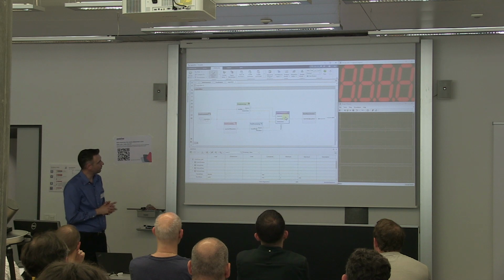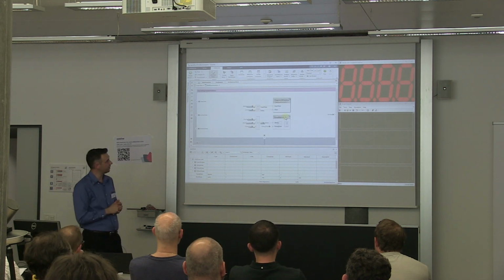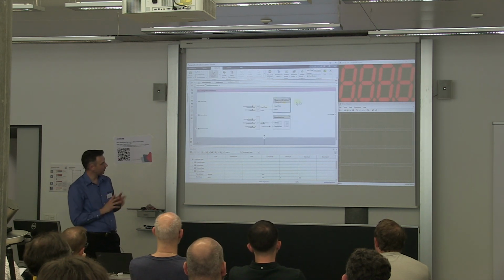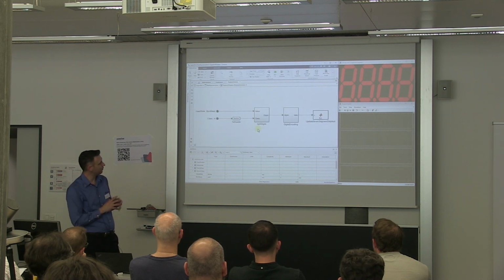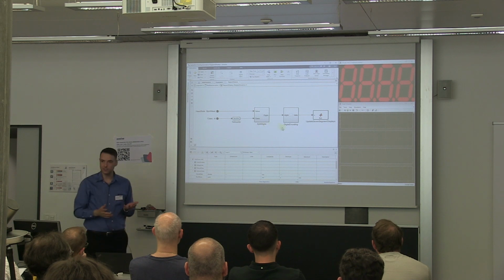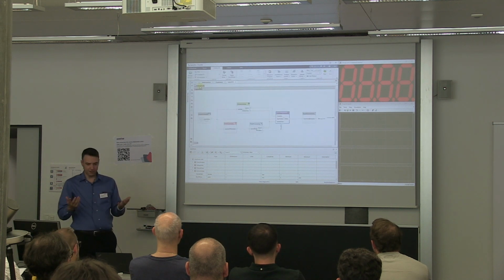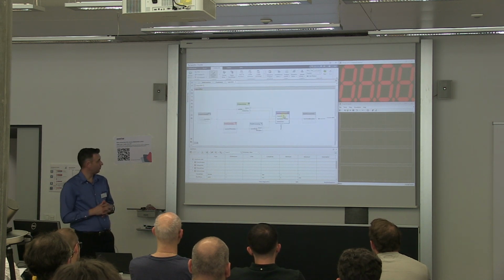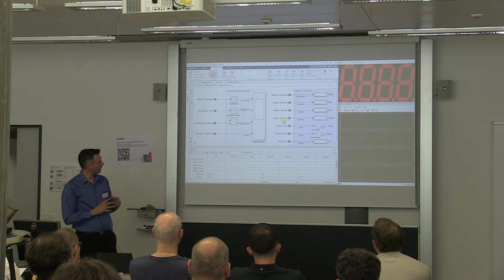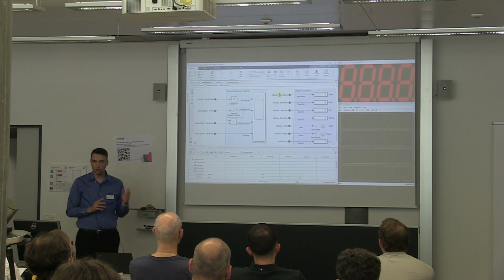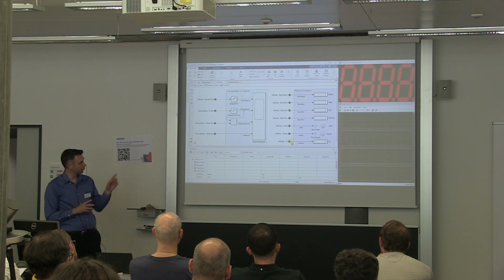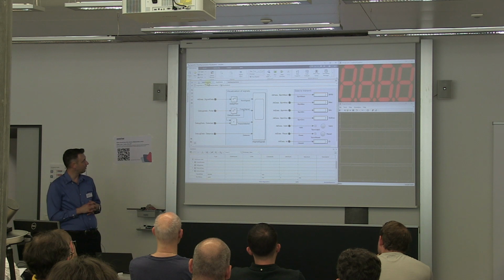And also, you can see that I have emulated the 7-segment display in the upper right corner. So here you can create an emulator in MATLAB directly and connect it to Simulink. And from there I can already simulate if the encoding of the digits is correct for my specific application. And all of this can be done already before going to hardware. And also we have the possibility to directly visualize all the data within the model. So you just need to select which signal of the bus you would like to visualize, and then you can run the simulation.